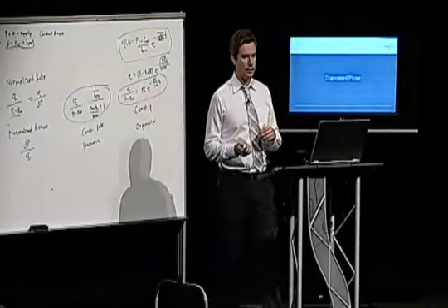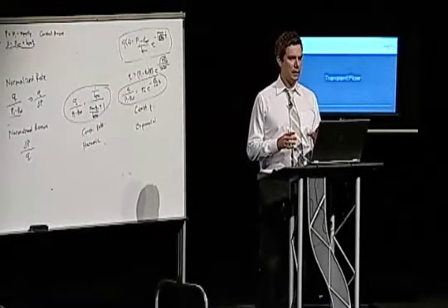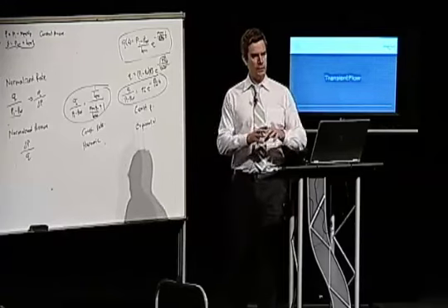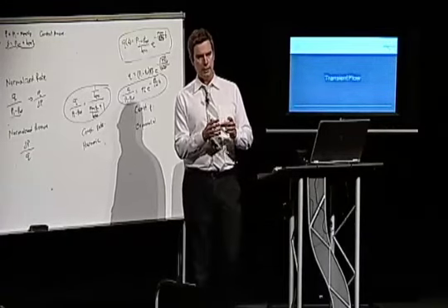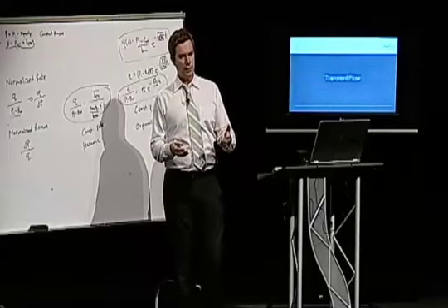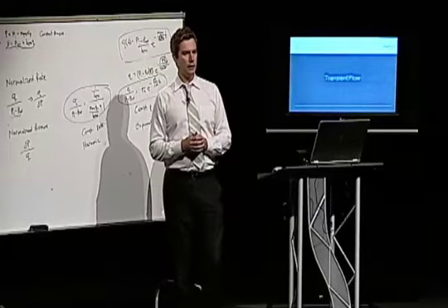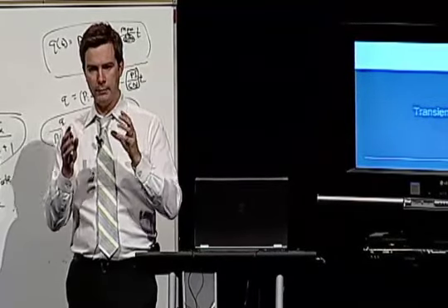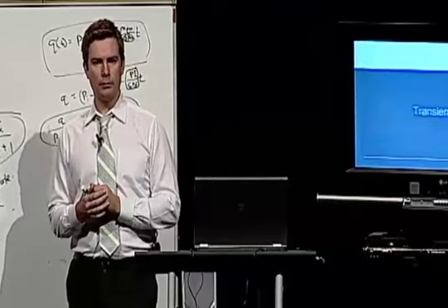Now I want to switch over to transient flow. We're not going to spend as much time in the theory of transient flow. I really put the emphasis on the boundary-dominated flow. Again, the reason being is because we normally assume that production data is going to be dominated by boundaries over time. Long-term production data analysis is really a depletion or boundary-dominated flow problem.